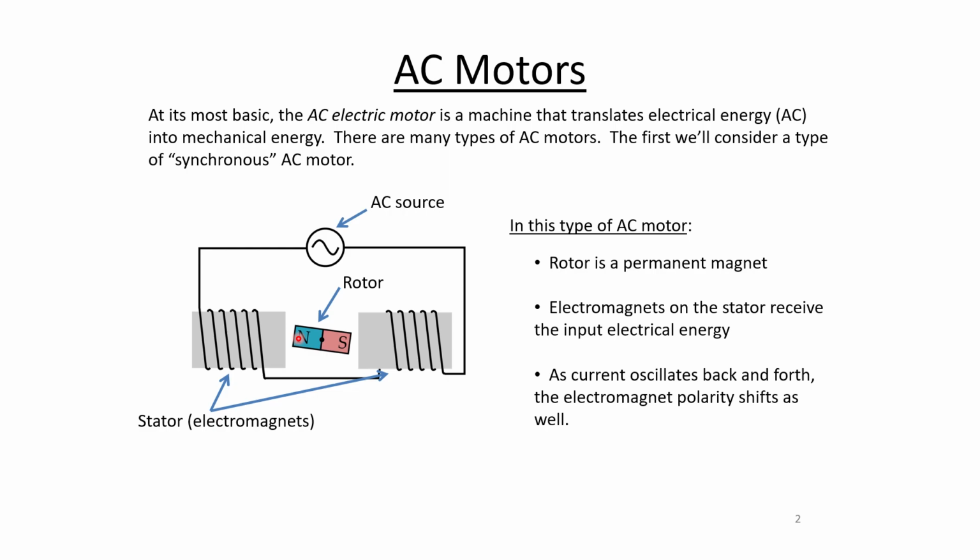In fact, what we usually talk about with AC motors is the idea that the direction of the field rotates, so goes around and around in a circle around the stator. Now here it's going to be a little more difficult to see because we only have two electromagnets, but when we get to the example that we'll have at the end of this video where we have four electromagnets, the idea of rotation, quote unquote, of the magnetic field created by those electromagnets should be a little clearer.